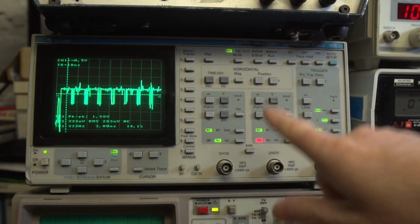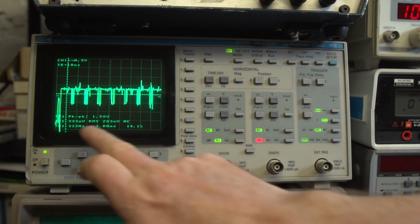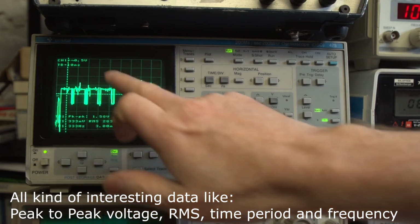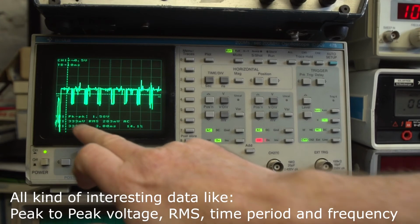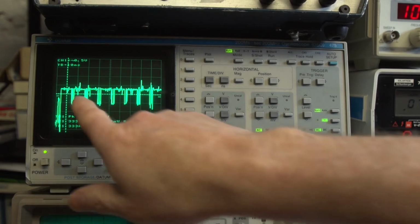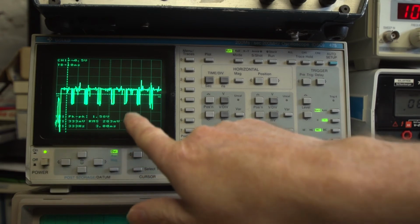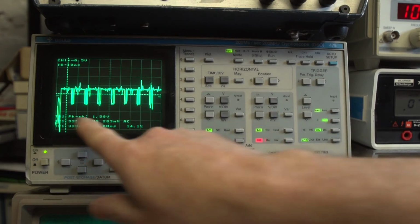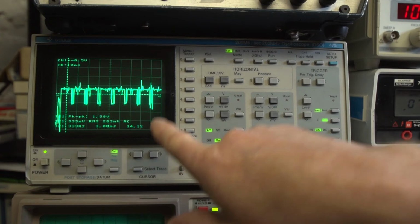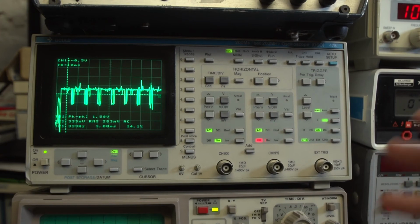The other advantage with scopes like this, and modern scopes are like this as well, all of the new ones that you can buy now, they have built-in mathematics functions which calculate the peak-to-peak voltages, the RMS voltages, and also the time period and the frequency. So the time and frequency calculation that we did earlier is actually done internally here and displayed on the screen for you in real time as well. As you vary the input signal, it would be constantly recalculating what the values are, so you don't have to keep getting your calculator out all the time, which is extremely handy, especially for things like frequency readout.